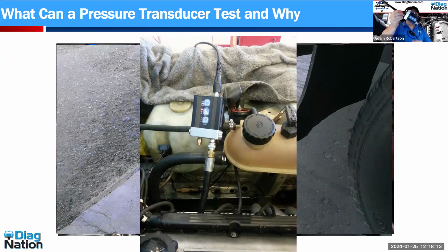I want to take a pressure transducer and a compression hose, pull the spark plug out, stick this in, hook it up, and read all the pressure changes in the cylinder. No doubt, wicked cool diagnostics, wicked cool. And here we go again, another class all in itself.